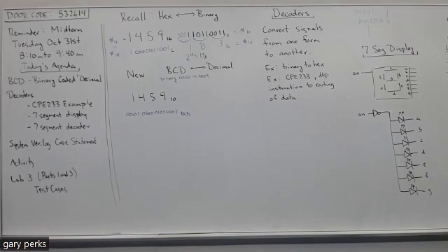But if you take a look at the decoder, on the left side, which is the input side, up towards the top, you'll see a little tag symbol, and it has IR, and then in square brackets says 14 to 12. The IR stands for instruction register. Okay, we're going to learn what registers are in a few weeks also. But the instruction is referring to a microprocessor instruction. And the 14 to 12, that's referring to 3 bits of that instruction. And then right below it is IR 30, so that's instruction register, the 30th bit.